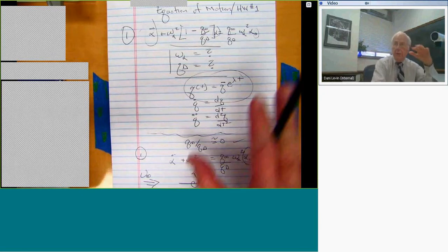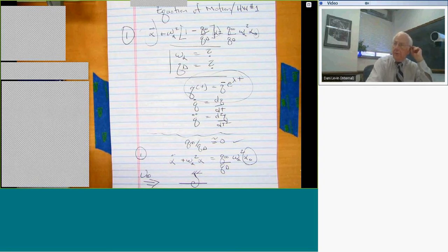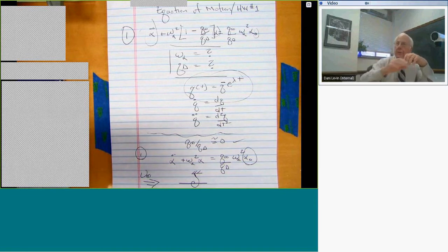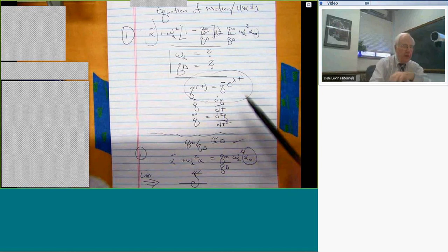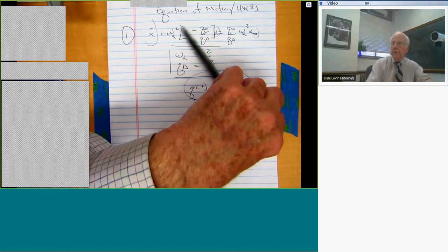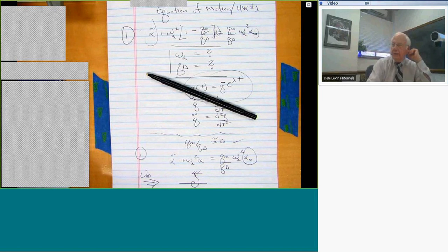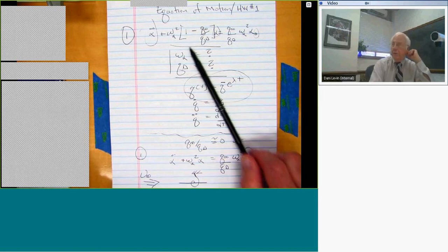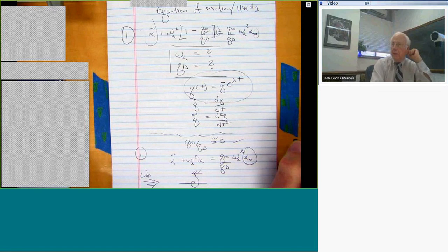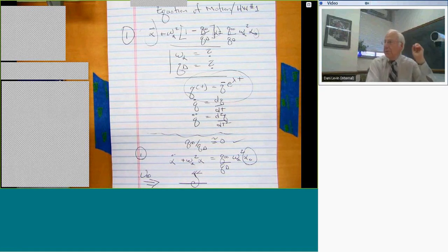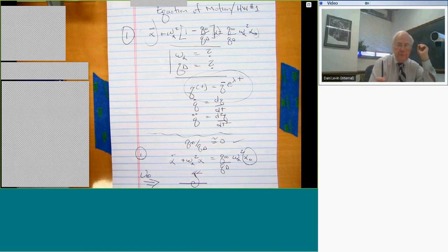And again, in this problem that we're talking about, there are at least two frequencies of interest. There's omega alpha, which is the in-vacuum natural frequency when the aerodynamics are not acting. But when the aerodynamics are acting, then it modifies it, and there's now a new frequency, right? And as you point out, if you just look at this coefficient in this simple model, you can clearly see when it changes sign. It changes sign at Q divergence. Of course, you don't know what the Q divergence is, but I'm sure you can figure that out. Okay, so does that help? Thank you. You're welcome.